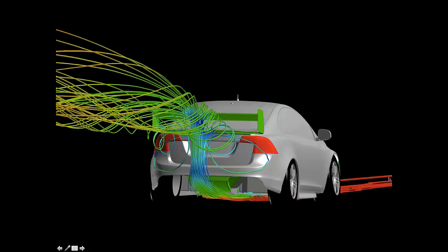So here we go. I've got the diffuser and wing highlighted. This image sort of shows how your wing and your diffuser are working in tandem. They work together to help drive the flow upwards. As I said, it's difficult on a V8 supercar because the diffuser's not quite as active because your floor's got quite a lot of elements under there. If you've got a flat floor car like a GT3, it's generally much more effective having a diffuser in there, and if you can get a wide diffuser with lots of strakes in there to stop the turbulence from the wheels and things getting in, it makes them even more effective.